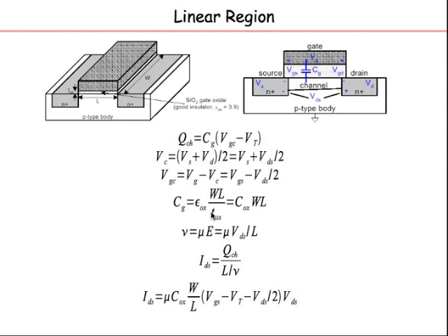And there is a velocity of at least the charge mass. There is an average velocity called the drift velocity, that is V. And that velocity depends on the mobility and the electric field. The larger the electric field, the faster it will go. So there is a mobility factor here, and the electric field is VDS by L. We are talking of this lateral mobility, lateral electric field, VDS. The gradient of voltage is the electric field, right? So VDS by L, L is the channel length.